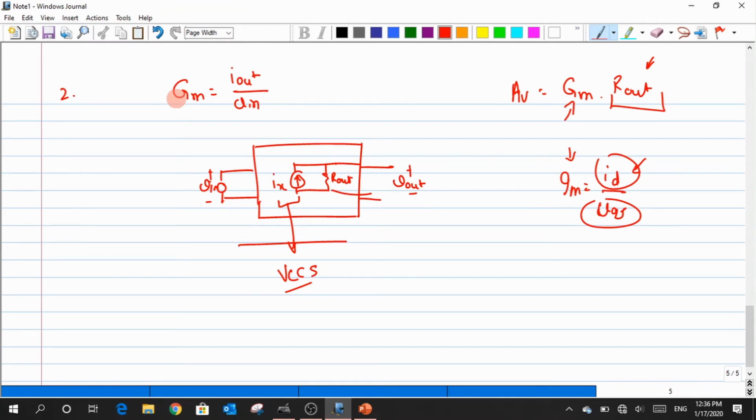Short the terminals, yeah. Exactly, whenever you want to measure any current, you need to make the current flow through the device and through an ammeter, which means that you need to short those terminals. So whenever you short this particular point, the Vout goes to 0, but obviously you will end up having some sort of I out current through this short circuit. In general, I can state this I out is nothing but a short circuit current.